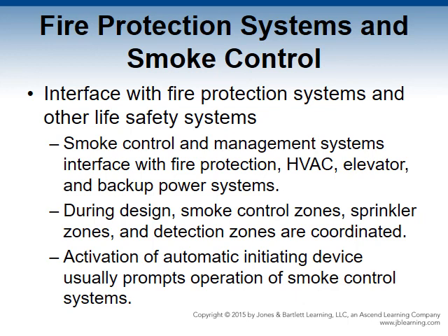Dampers on air supply and relief systems will close. HVAC systems turn on or shut down. Elevators can locate at predetermined floor levels. And backup power systems are ready in case of loss of power to the smoke control system.